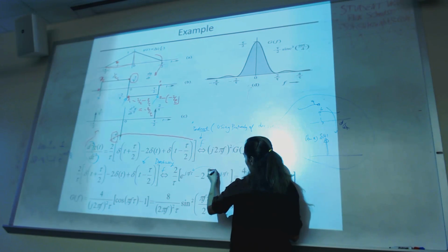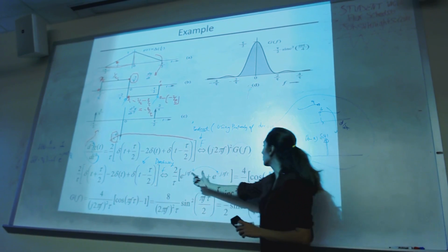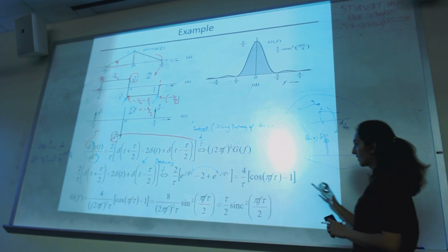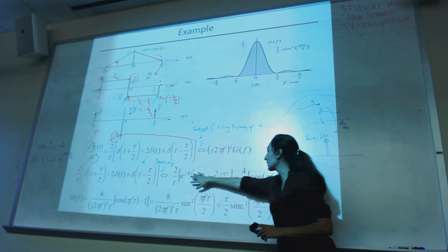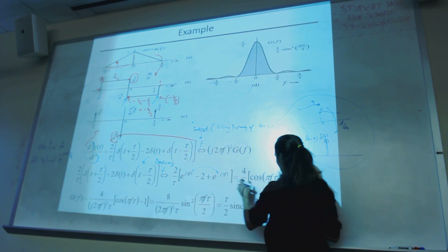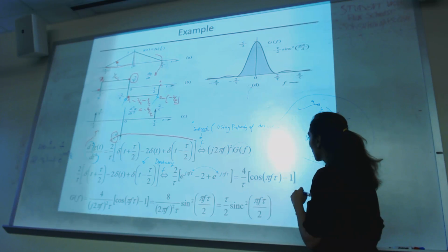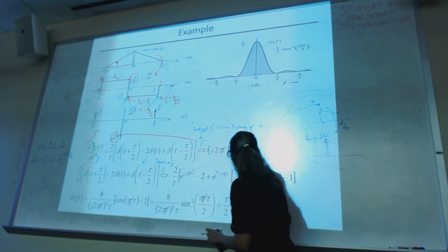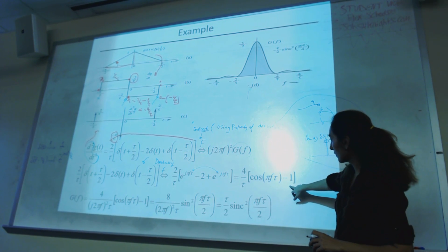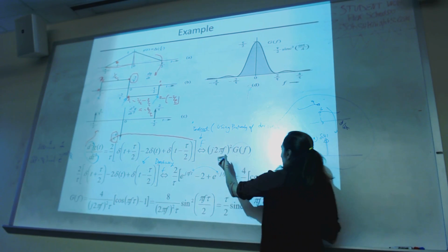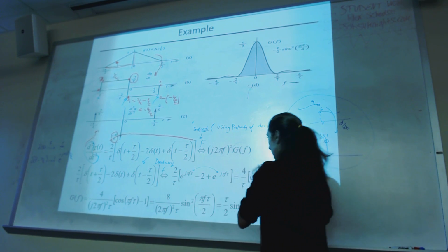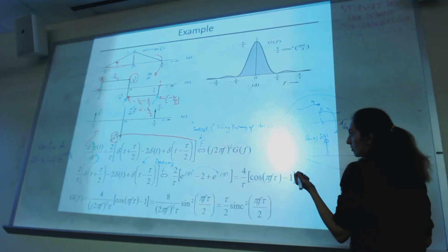This is 1, this is some exponential, then this is exponential. So hopefully by now, when you see these 2 exponentials together, it reminds you of e to the power of j theta, e to the power of minus j theta. Cosine. So we get a cosine for that, and then just type this up at 2. So we get this. Okay, so now make these two equal because both of them are a Fourier transform of the same thing, just from two different methods.